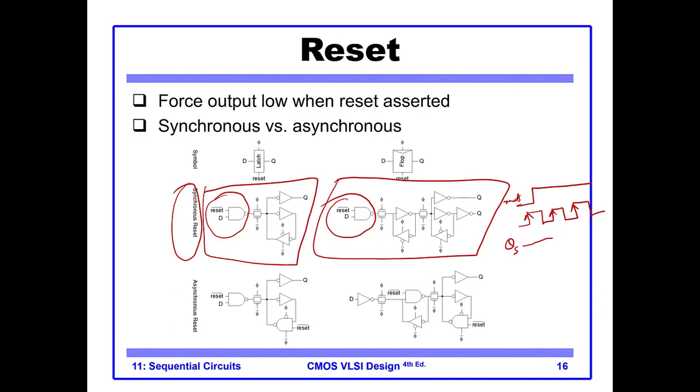Let's say this is some previous value, and when this positive edge comes, the output will become 0. So it is reset here. Although reset is 1 in this duration of time, it has already missed this positive edge. On the first edge it was 0, so it is not considered, and on the next one it is considered.